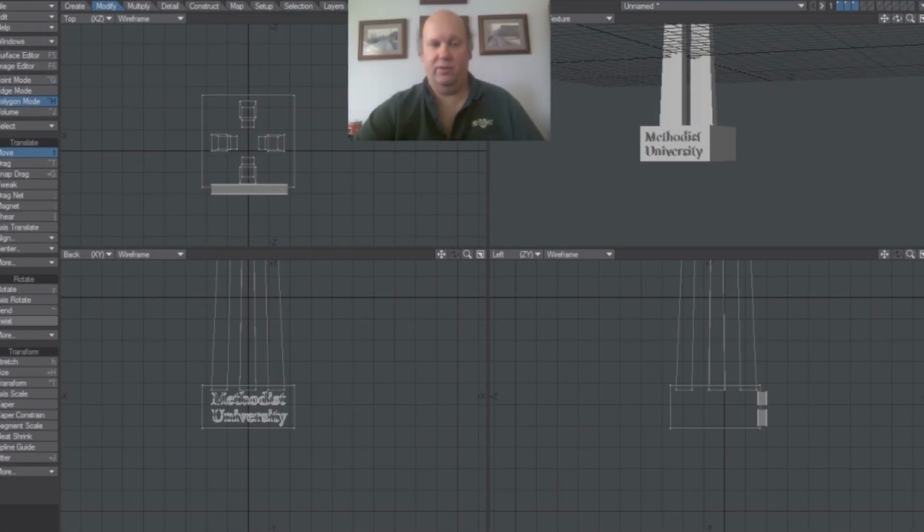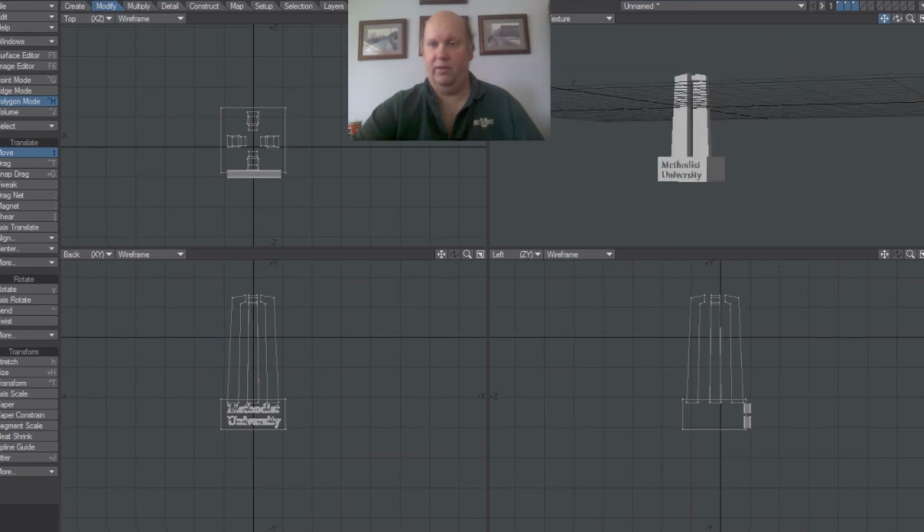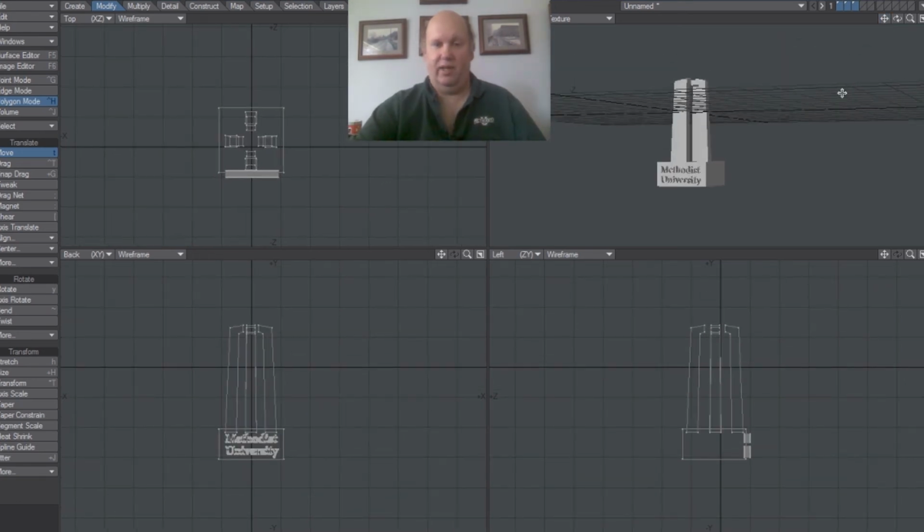Okay, so at this point, what we want to do is get the logo ready for the 3D printer. And really, there isn't much to that, except for one thing that we have to start with. We're going to print this out as one piece. Right now, it's in 3 layers. If I export this as an STL file, which I'll have to do to print it, it's only going to export 1 layer at a time. So I have to flatten the layers.